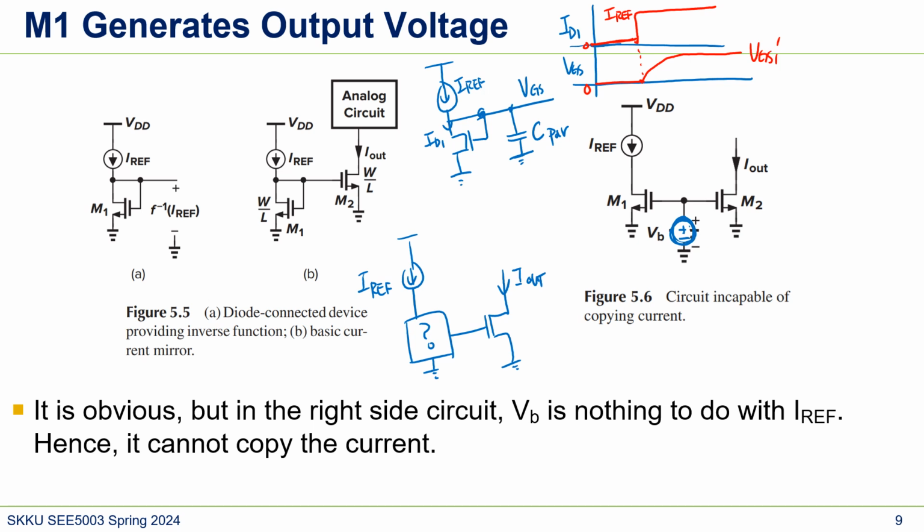The reason why the voltage increases is that when VGS is 0, let's say this voltage is 0, this MOSFET is turned off, right? If this is turned off, the current has to flow to this capacitor, right? Since the current flows here first, that's why the voltage increases.